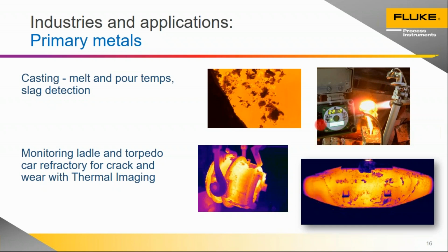With the fiber optic sensor, you have the detector and the electronics located safely away from the high temperatures involved. We did have a gas flame torch pointing right at that cast line, so extremely hot temperatures in this area. If you use a fiber optic sensor, you have just a simple optical head with no electronics inside it. You're able to get that very close to the pool that you're measuring.